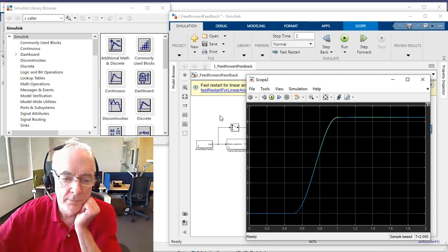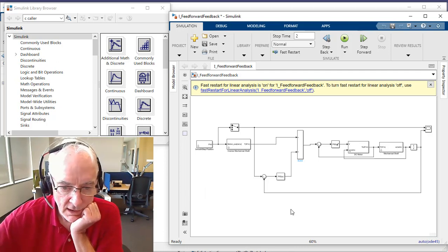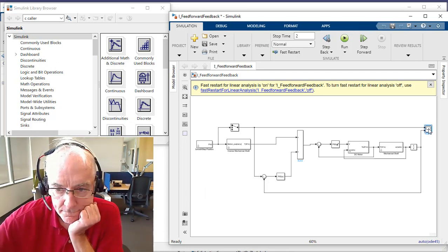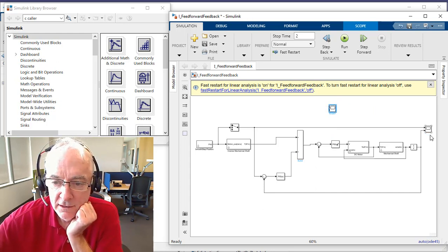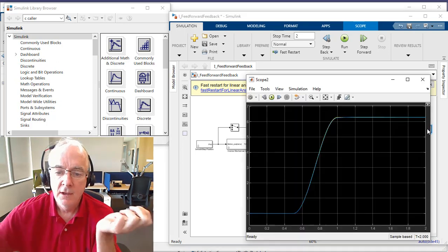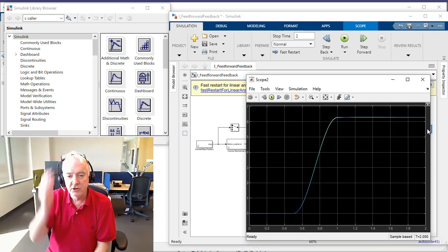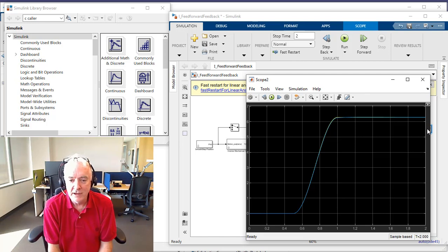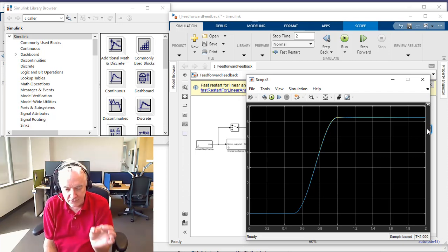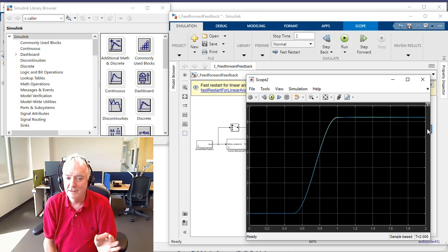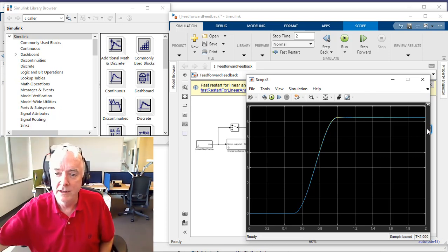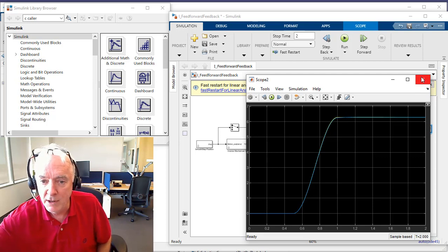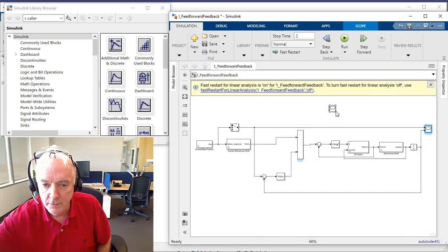Okay, so a couple things. I want to get into this comment about maintenance and understanding the deterioration of your equipment, because what we're seeing is that if you designed your controls really well, you can't really look at the machine and say it's deteriorating. It's doing what it needs to do. But maintenance is very much about understanding that the onset of failure is coming. And that absolutely is revealed in this model, but you're just not going to see it in the command in motion because the controls are working so well.